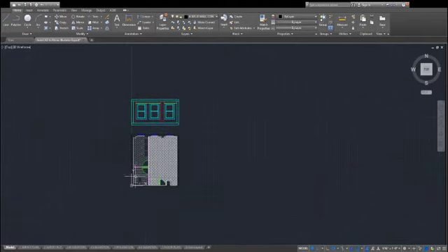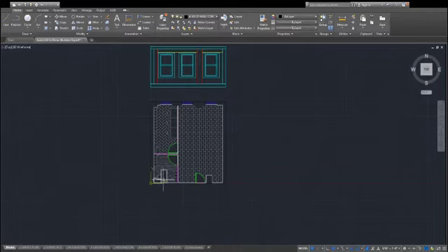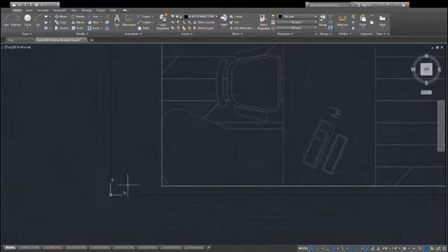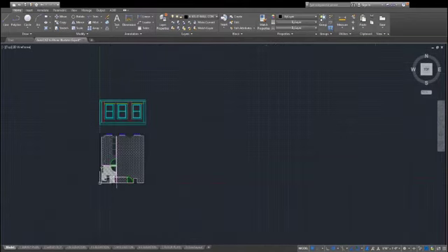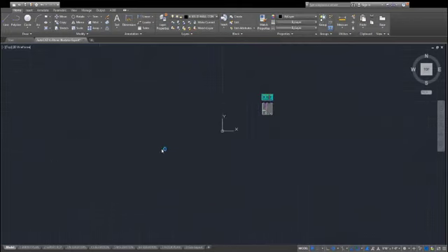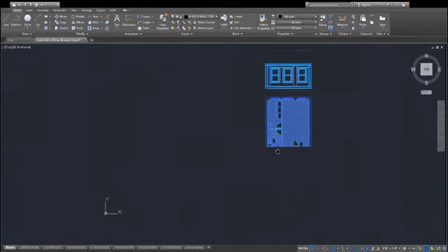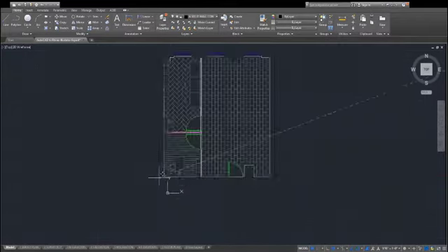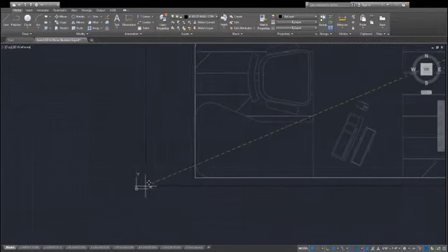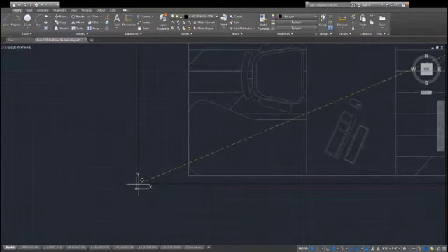And in order to do that, the best way is to make sure that your drawings are within the 0, 0 coordinate of your XY UCS, or Universal Coordinate System. So by some chance, if your drawings are way off here, and again, if you have many drawings because it's a big project, you should have drawings all over the place, in which case make sure the portion of the drawings that you would like to work with in the other software lies preferably within the center portion of the XY coordinates.